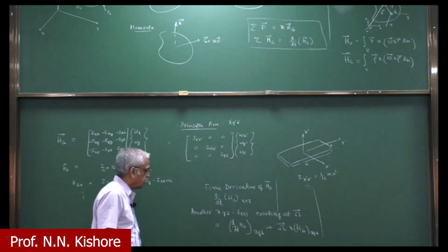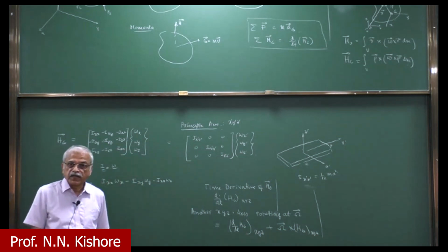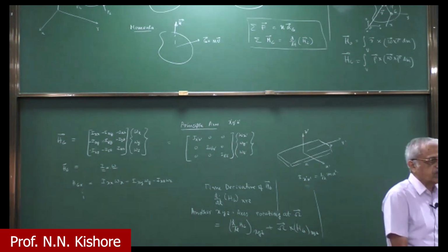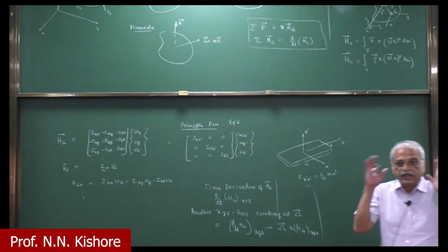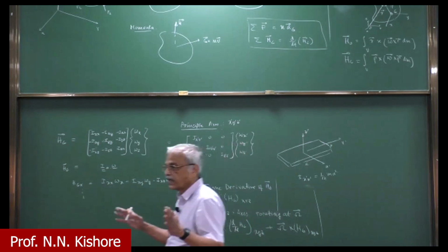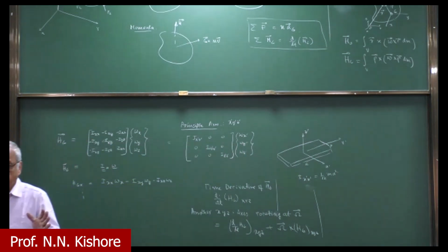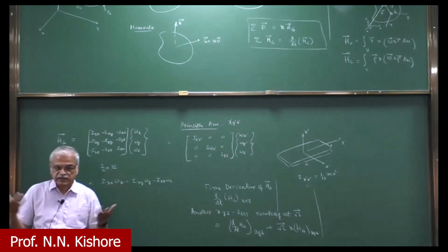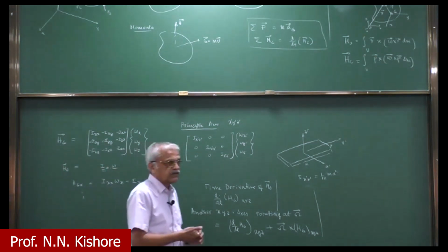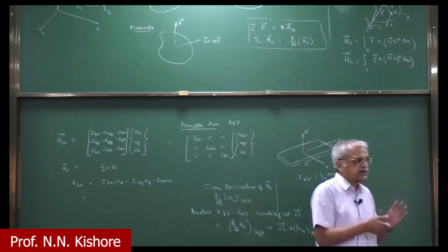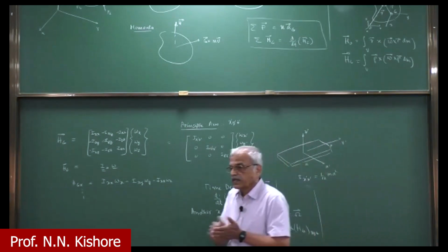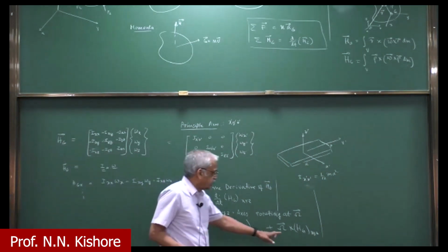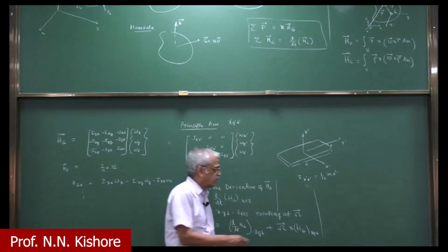So there are situations where we can conveniently find this big omega, where inertia terms will not change with time. Ultimately what we want is a simple big omega wherein the inertia terms will not change with time. Of course, angular velocity has to change, since we want to find the acceleration. But at least we don't want the inertia terms to change, so we have to make an appropriate choice.